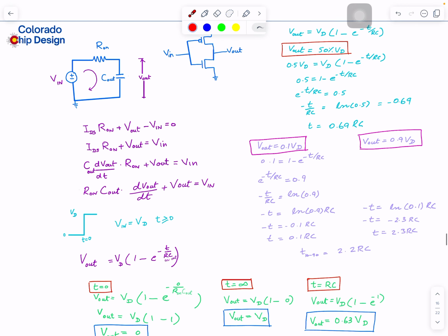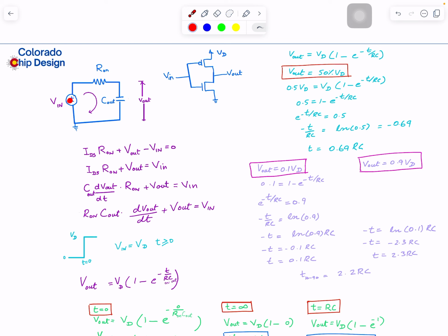If you remember, I'm assuming that from the output side, the transistor acts like a resistance and a capacitance in series, and in this case, think of just NMOS. So our output voltage here is really the voltage across this capacitor. Think of this as a capacitor connected to ground, and what is driving it is like a Thevenin equivalent: a voltage source, which we can assume is the same as the input, because that is really the thing driving current here. And then there is an on resistance, which is part of the source. The source is not ideal; it will have some resistance.